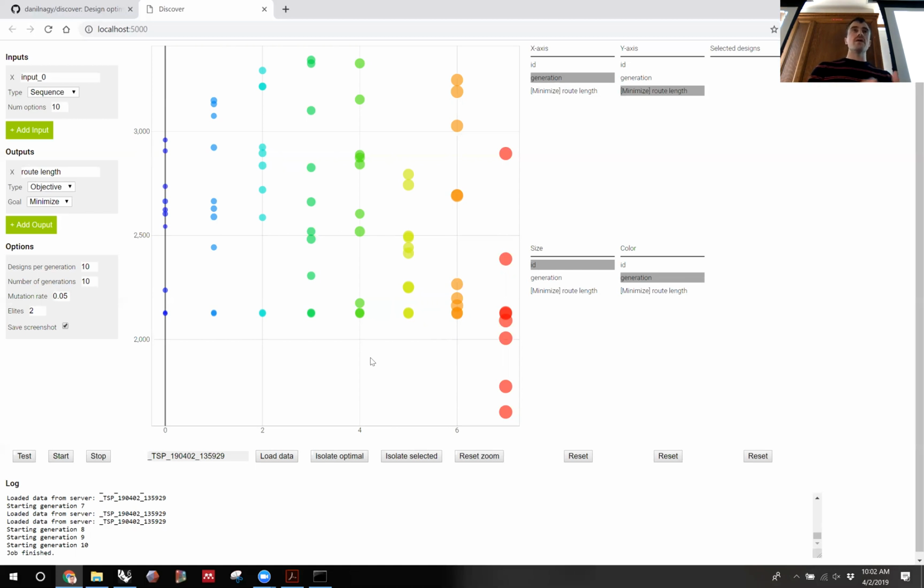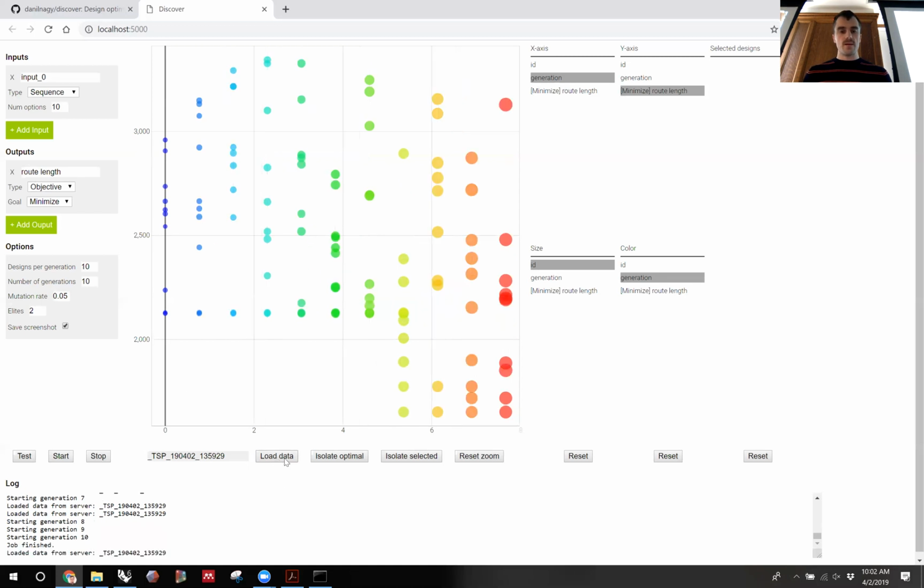But you also want to maintain enough diversity in each generation to make sure you don't get convergence on a local best solution, or even worse, a divergence. If you don't have enough designs in the generation, you can actually lose good data from one generation to another, or there just won't be enough diversity to find anything useful.